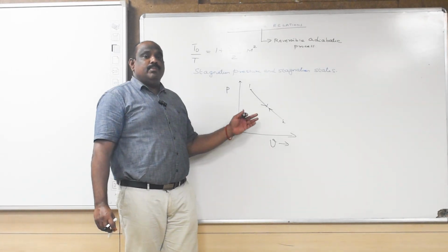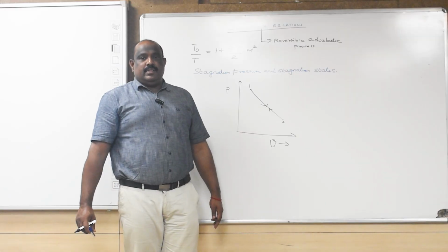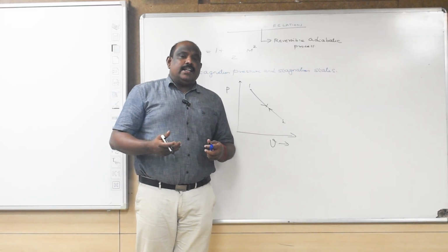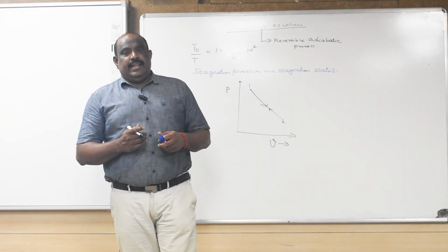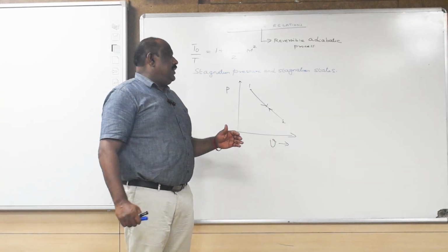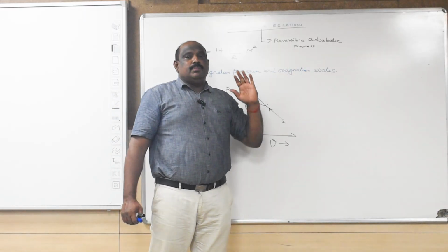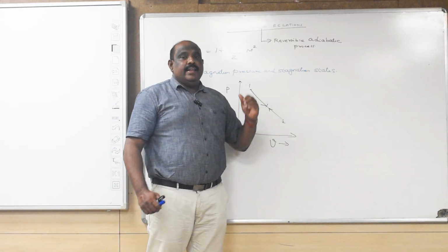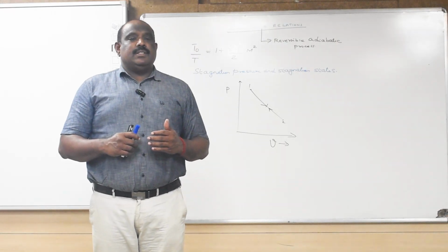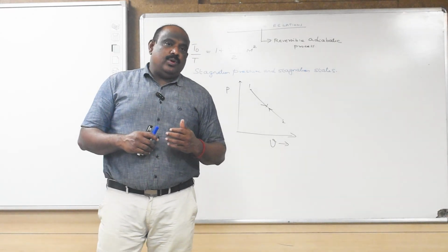Then you may have a question: why do we have to study this reversible process? Whenever you are doing a process, we try to get as close as possible to reversible, then our loss will be less. Based on that only, we go for the reversible process, and one such process is the reversible adiabatic process. In an adiabatic process, there is no heat transfer.